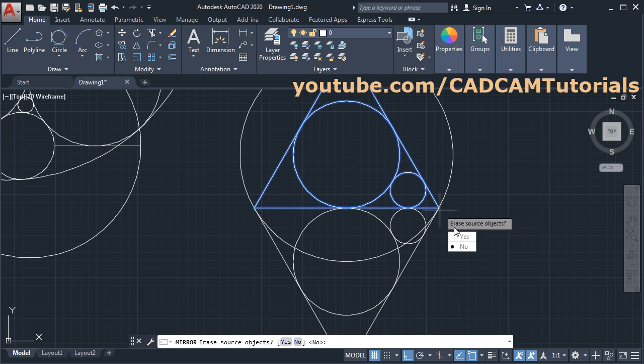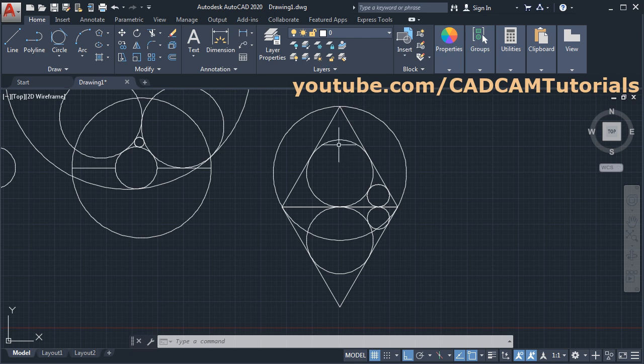Then specify whether you want to erase source object. So here I don't want to erase the source object. If you click on yes, the previously selected objects will be erased. I don't want to do that. Therefore I will click on no. So in this way this object has been mirrored around this line.